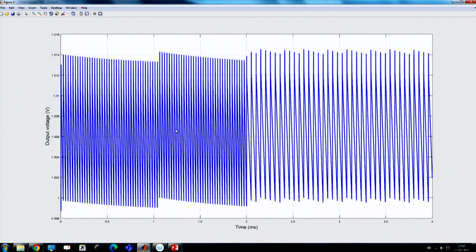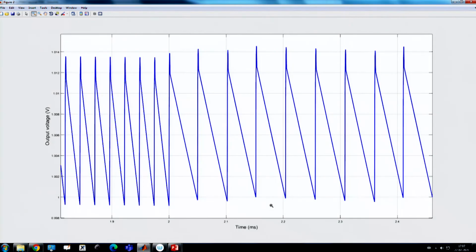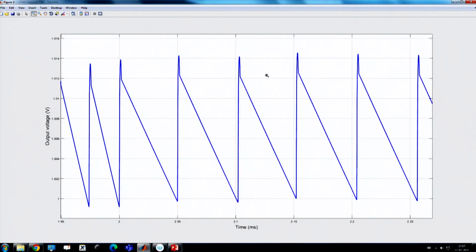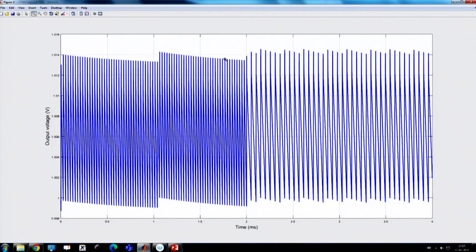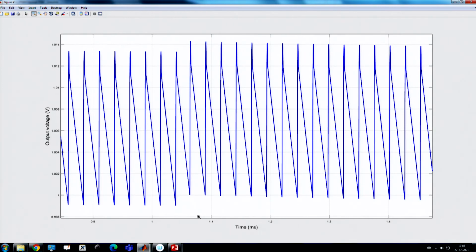The other thing you will find here is that there is a charge pulse, and if the load current decreases, more skip cycles happen. But this pulse skipping modulation has a problem of non-monotonic spectral composition. Because the number of charge and skip pulses may not be exactly balanced for any arbitrary load and input voltage condition, after a subsequent number of charge and skip pulses it can undergo an additional charge pulse or additional skip pulse.